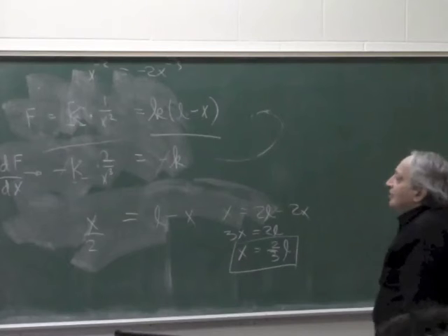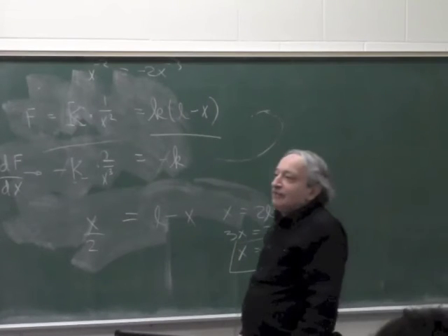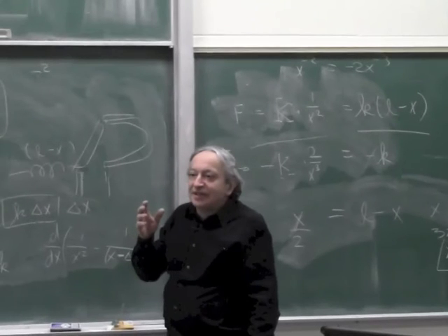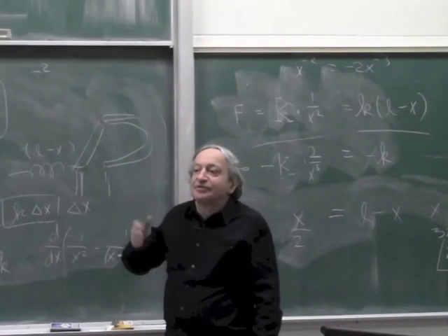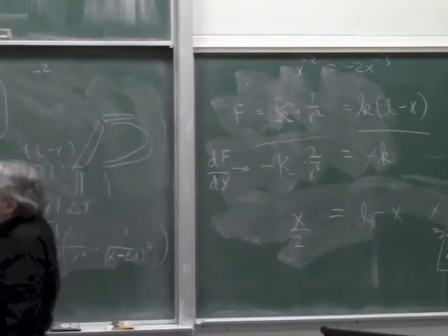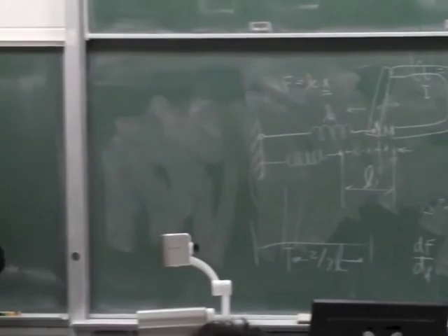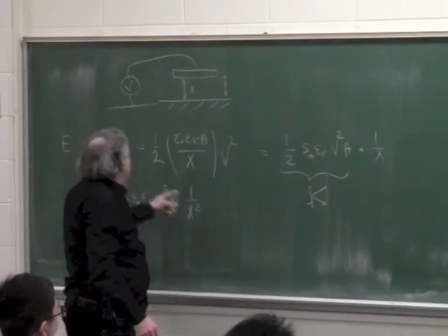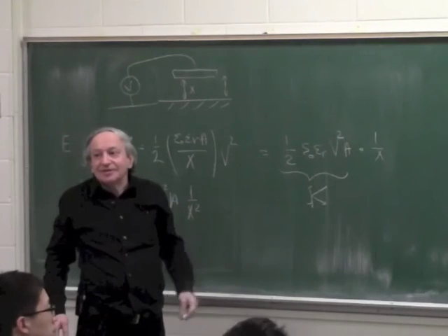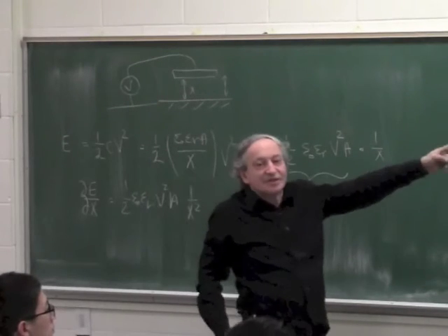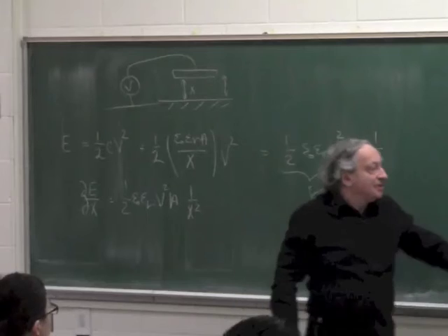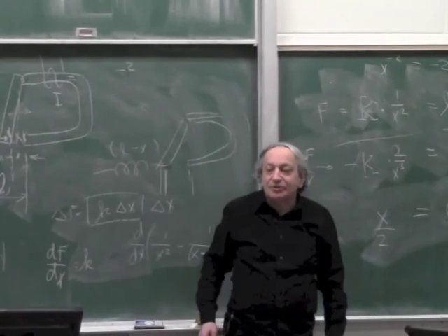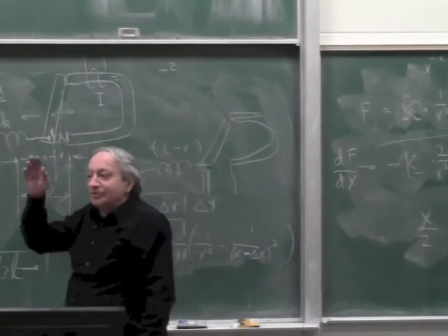Good. Okay. So bottom line, when I have a moving iron actuator, and if you think for one second, this will be true for any 1/x² actuator, because if I did the same analysis for this, I'll get the same results, because this part is a constant, so the rest of the equation is the same. In this case, the K is the K of the moving iron, which was 1/2 I squared mu A and all this.